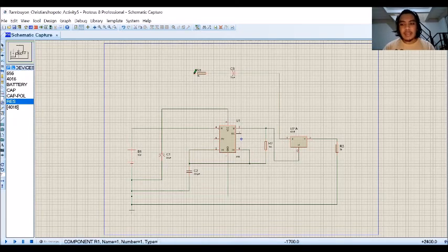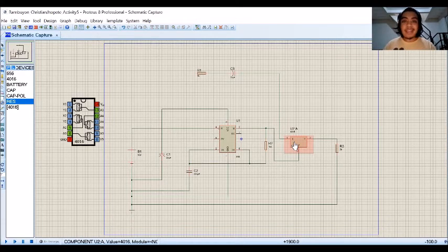Now let us discuss the 4016. This 4016 component is commonly used in multiplexing applications. It can also be used to isolate signals. The switch is bilateral and hence can be used for both digital and analog signals. The IC can operate from 3 volts to 18 volts but is commonly operated at 5 volts, 10 volts, 15 volts nominal voltages. You can switch voltages up to 20 volts.